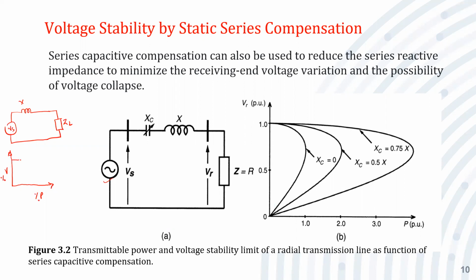It is found that for the uncompensated line, it depends upon the power factor. As the power factor decreases, say 0.9 and 0.8 power factor, the voltage stability also decreases. Whereas for the leading power factor, the voltage profile is not constant and it increases because of the unity or leading power factor.